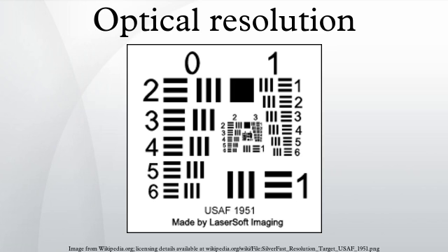The speed at which they can be sampled depends upon the decay rate of the phosphor used. For example, the P46 phosphor has a decay time of less than 2 microseconds, while the P43 decay time is on the order of 2 to 3 milliseconds. The P43 is therefore unusable at frame rates above 1000 frames per second. See external links for links to phosphor information.